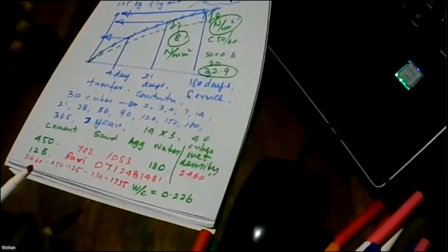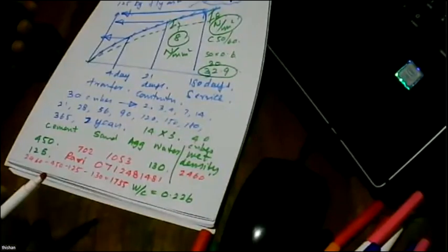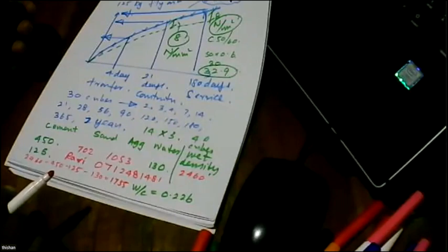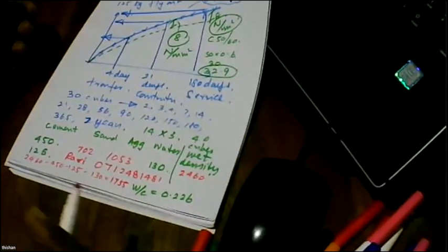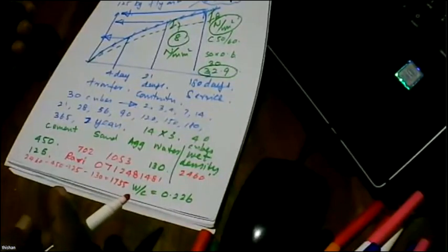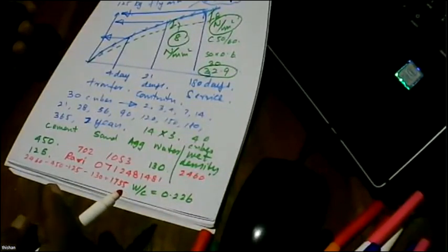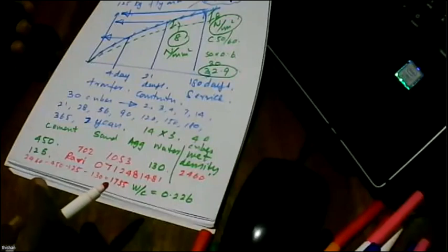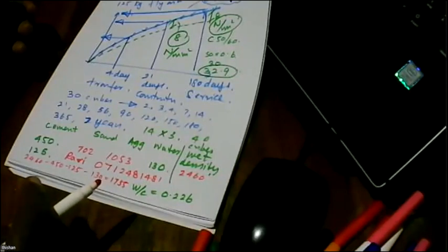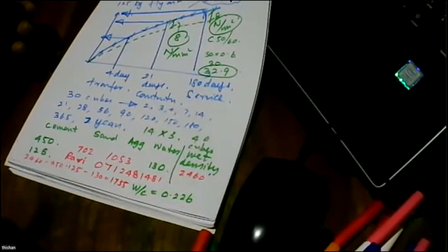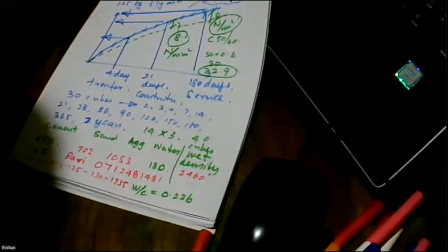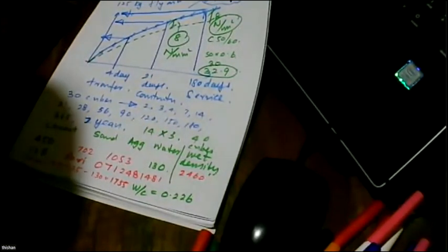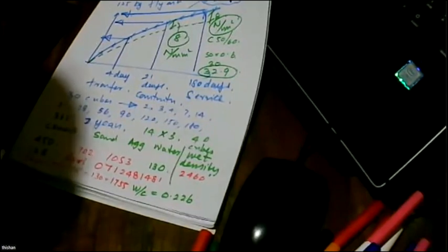So you can see Eurocode allows us to think aloud and go for very economical designs, because as we increase the strength, the strength range increases drastically, and along with the stiffness, that is the elastic modulus, we can actually optimize the beams to a great extent. So that's the kind of logic that we are working on. Is that clear? That's clear, sir. All right, good.